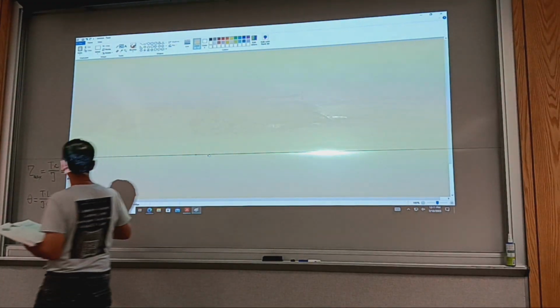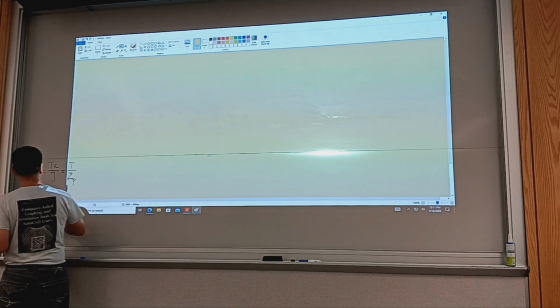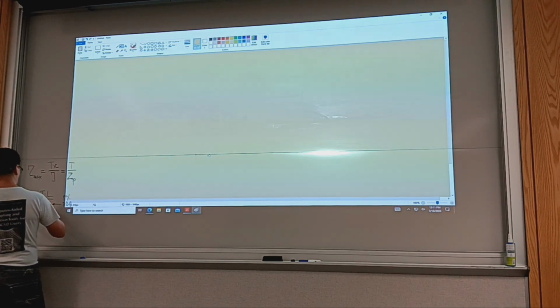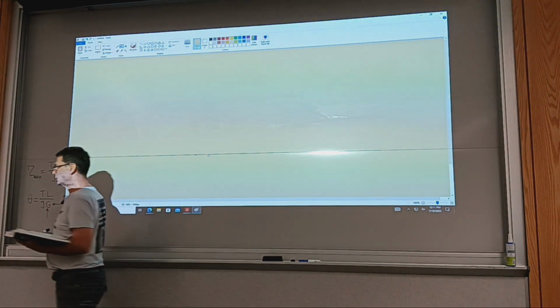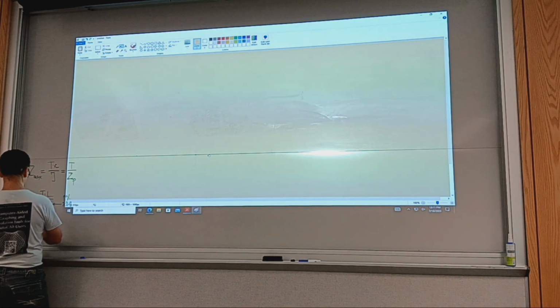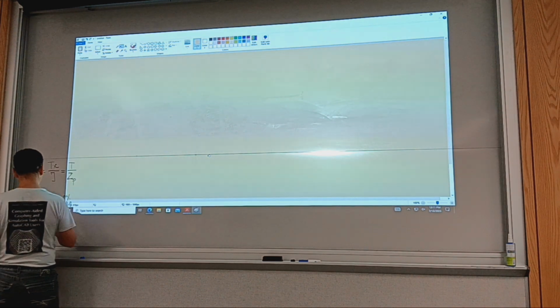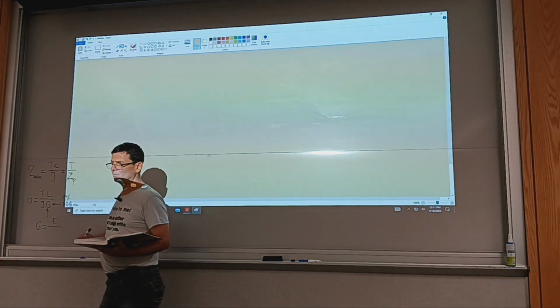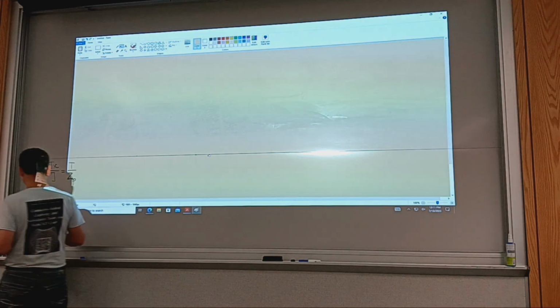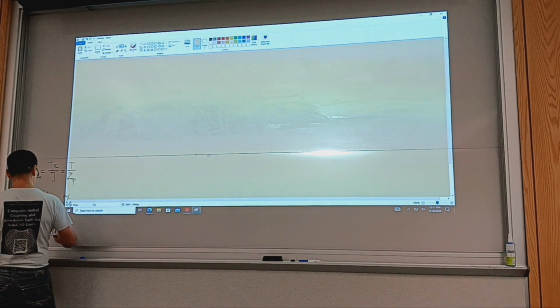And if not, you can use an equation on page 82, which says G, the modulus of elasticity in shear, can be calculated using the modulus of elasticity in tension, the Young modulus, divided by 2 times 1 plus Poisson ratio.